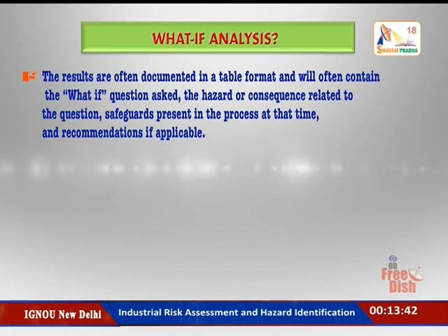The results are documented properly in a tabular format that will contain the "what if" questions which are asked, the hazards or consequences related to each question, the safeguards present in the process at that time, and the recommendations if applicable.